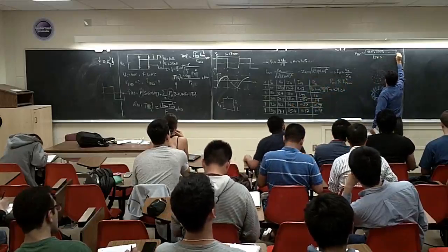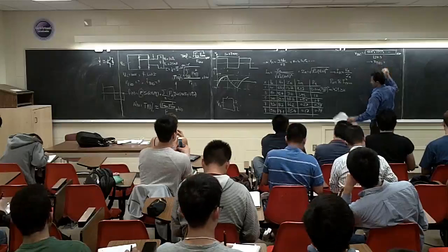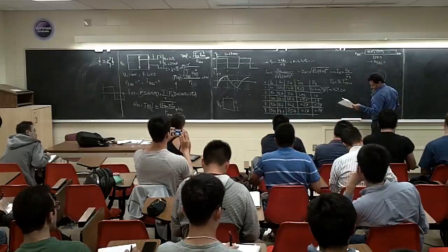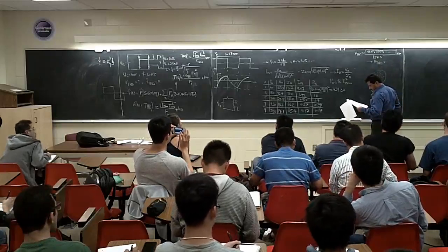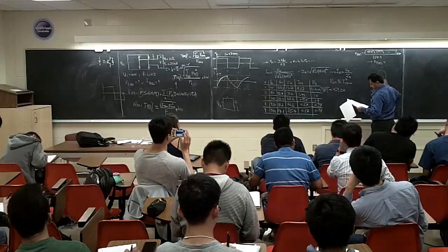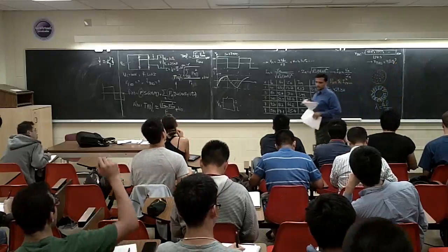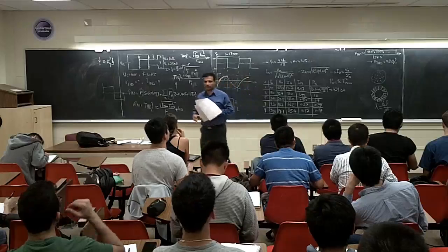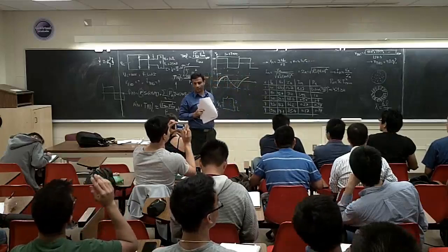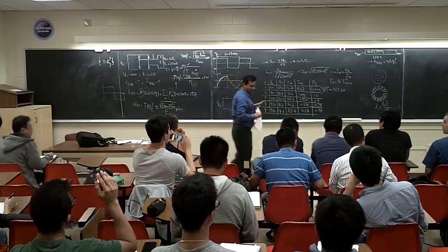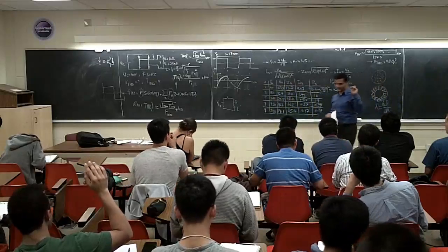127.3 times 100. So if you calculate this from THD, it's going to be 48. You know what's the standard number usually you want? 5%. There's a THD. The lower the better. Don't go the wrong way. The lower the better, yeah, 5%. Usually they want 5%. Think about how bad this one is.